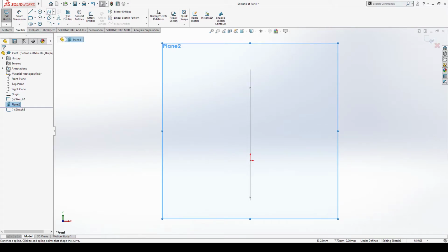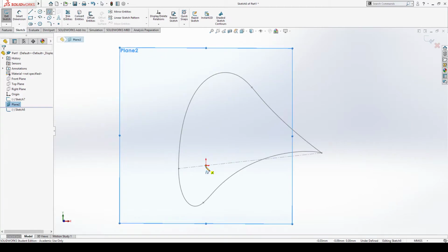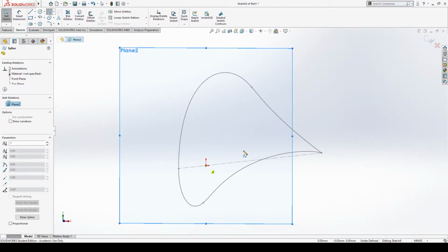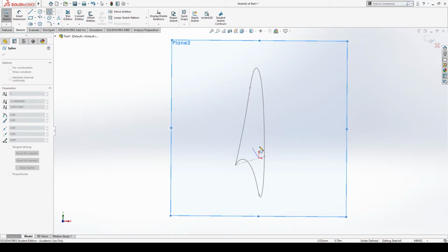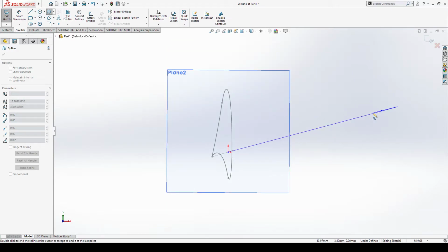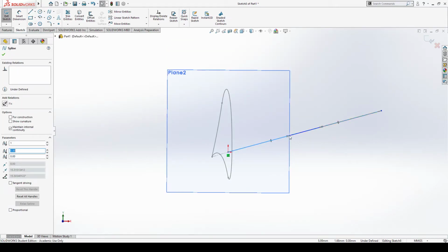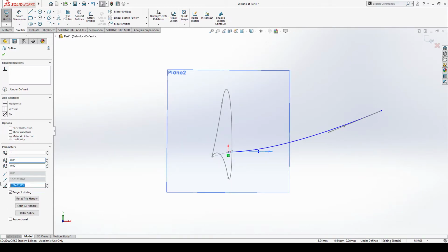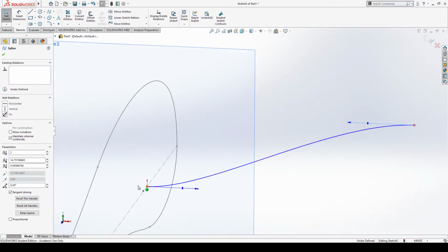And this is what's going to define the shape of the wing when you're looking at the wing from the front. So how it curves upwards. Just going to make sure we're inside it. The origin is definitely inside the aerofoil at that point. And I'm just going to draw out a simple spline so we can get some interesting curvature on the airfoil. Again, using this feature down here to set the angle of the start and end exactly as we want it. We do want the start point to definitely be horizontal.